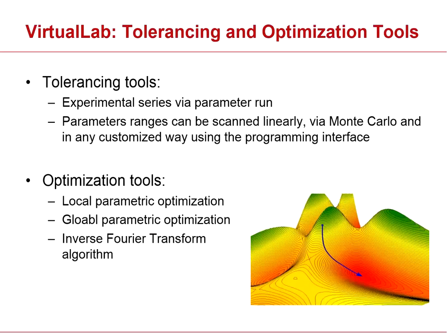There we have several tolerancing tools, especially the parameter run, which allows you to scan parameters in linear mode or also in Monte Carlo modes. And VirtualLab always has a programming interface where you can customize all your structures and also the parameter selection for such experimental series. Optimization tools include tools for local and global optimization, and also the Iterative Fourier Transform Algorithm, which is applied for the design of diffractive optics, for example.